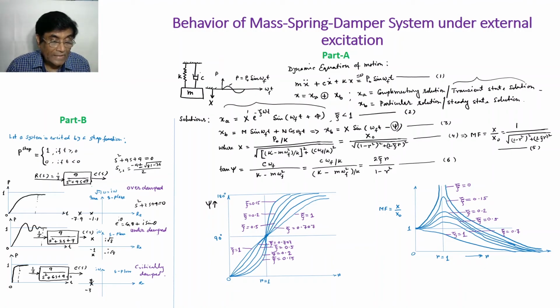You see, if the controller gain is adjusted corresponding to the critically damped situation, then if this is where I want my system to go, it will go very quickly. It will not go with a lot of delay. It will go very quickly. That's the reason we like the critically damped condition.